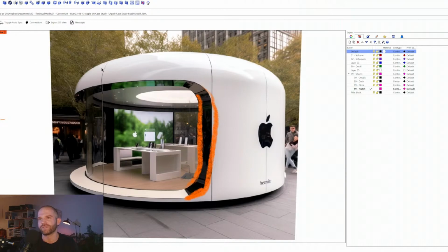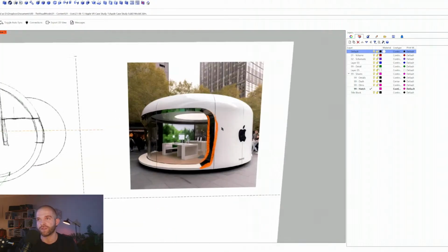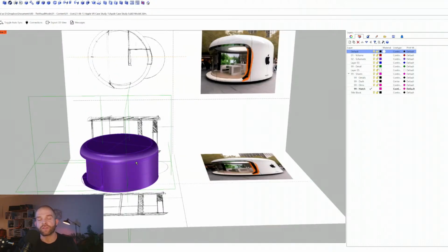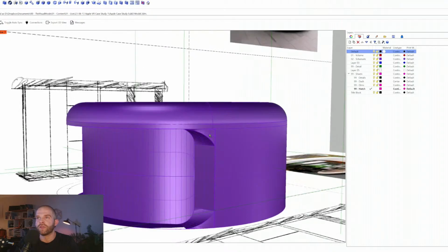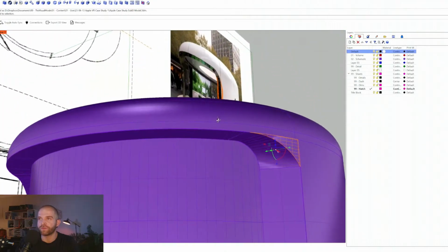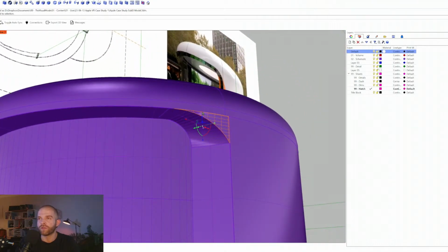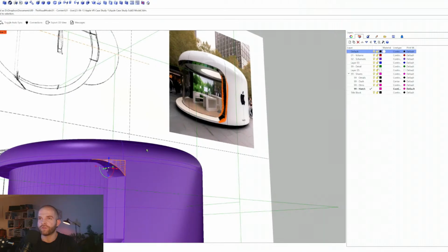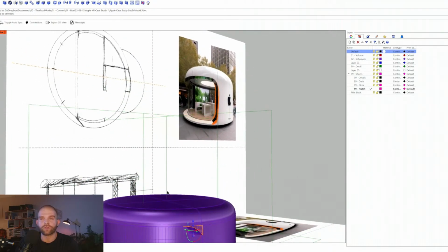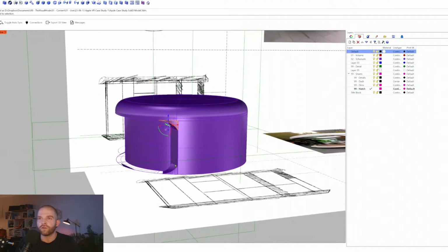Spatial activation is a case study I've been working on in order to come back to some of these Rhino tools that I find really useful for modeling and for basically just pitching designs. So what we're going to do is rebuild this using SubD modeling. The reason is that last time we had a little bit of trouble modeling this corner here specifically. So we're going to see if we can use the SubD tools to not have to use NURBS to create this curve here. We can always convert SubDs into NURBS if we need to for, say, fabrication or something.